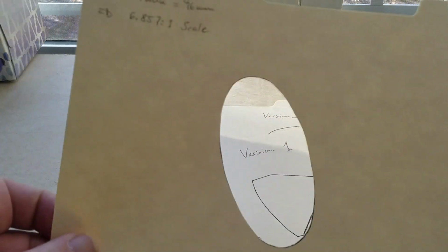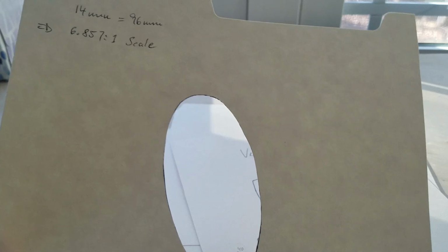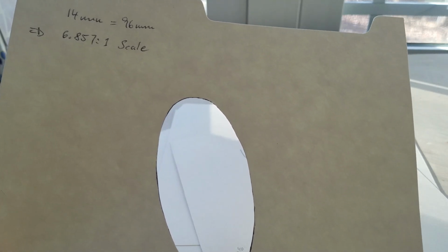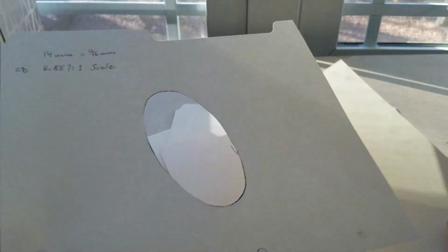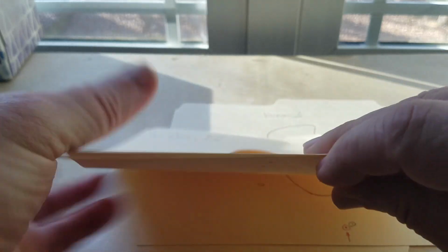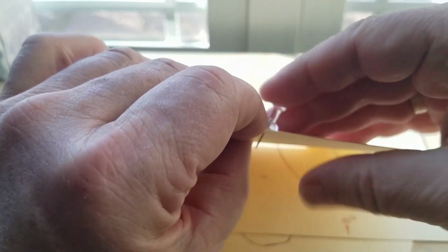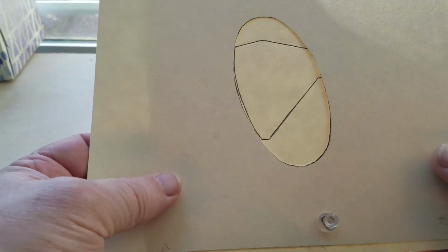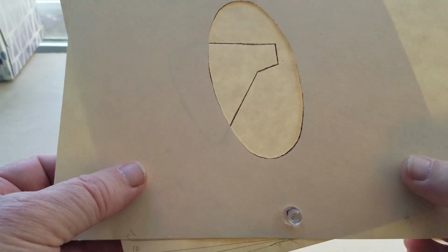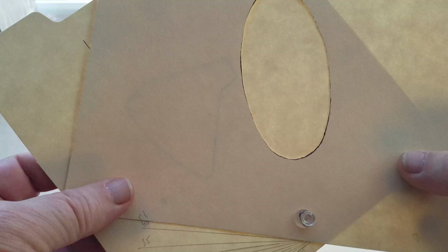I here got that gap in the auxiliary air valve, which is an ellipse, long axis 14 mm and short axis 7 mm. And what I'm going to do is this. I'm going to put a little pin through here, and here. And then I should be able to see my auxiliary air valve fully open, and then slowly close. And then I can correlate that with the angle.